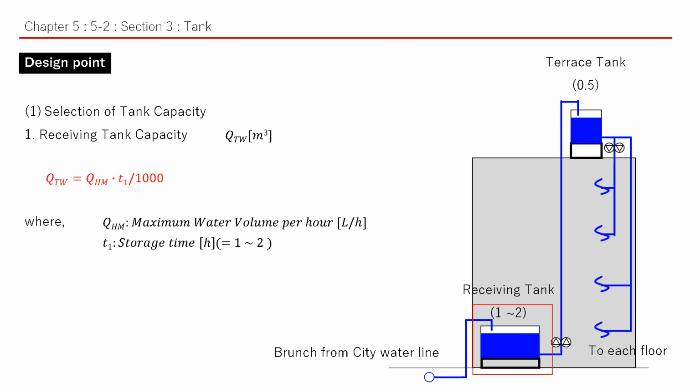Receiving tank capacity can be calculated from this formula. We consider storage time 1 to 2 hours basically. Next, for the terrace tank, we consider storage time 0.5 hours basically.